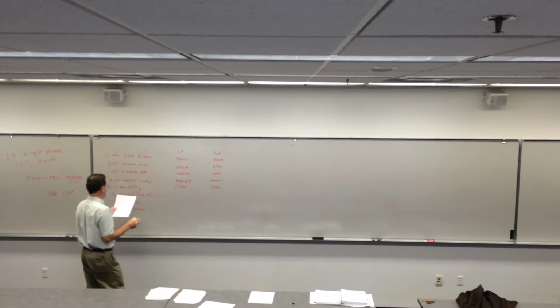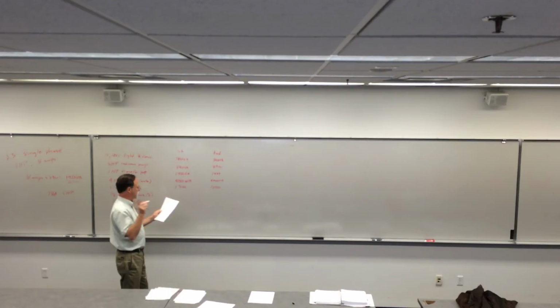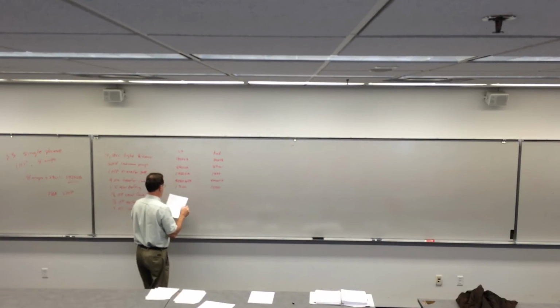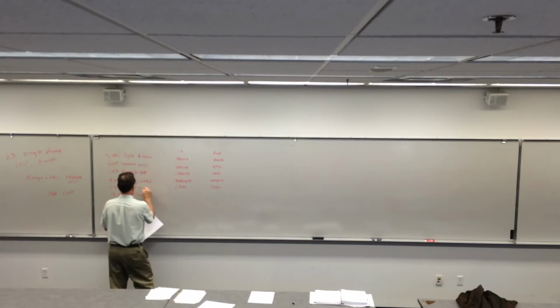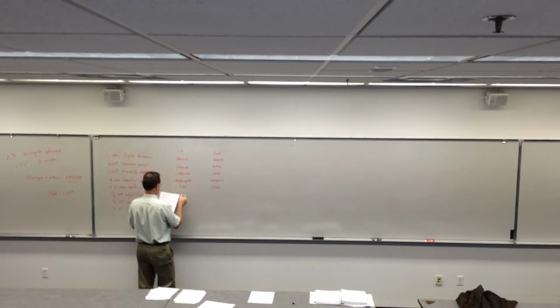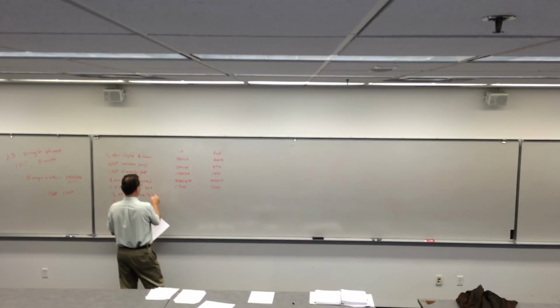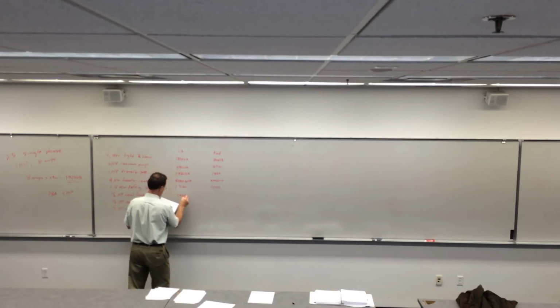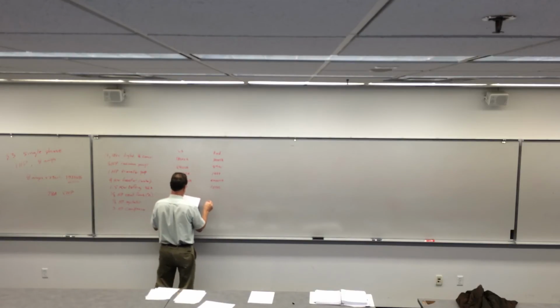Your 1/3 horsepower is 3.6 amps from the same table that Ashley quoted earlier. So that's 3.6 amps times 240 volts, which gives you 864 times 2, because there are 2 of these, 1720. And this is the part where I messed up.